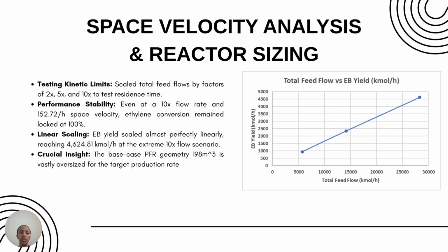And going into space velocity analysis and reactor sizing, what we did here was increase the feed flow by 2, 5, and 10 times to see how the reactor behaves. And surprisingly, even at 10 times, the reactor conversion stayed at 100%. So basically, all the ethylene that we are adding is reacting.